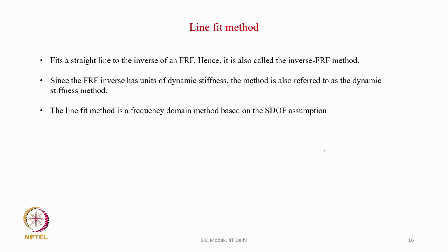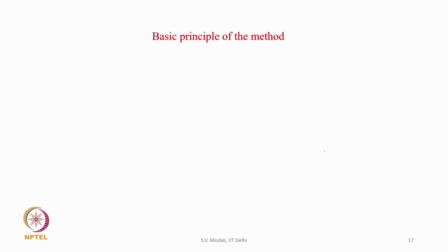This method fits the data in the frequency domain, so it is a frequency domain method, and it is also based on the single degree of freedom assumption. Let us look at the basic principle of the method. We know that the FRF of a multi degree of freedom system with structural damping can be written as the sum of the FRF contribution of the Rth mode and the contribution of all the rest of the modes. Here the first term is the contribution of the Rth mode,